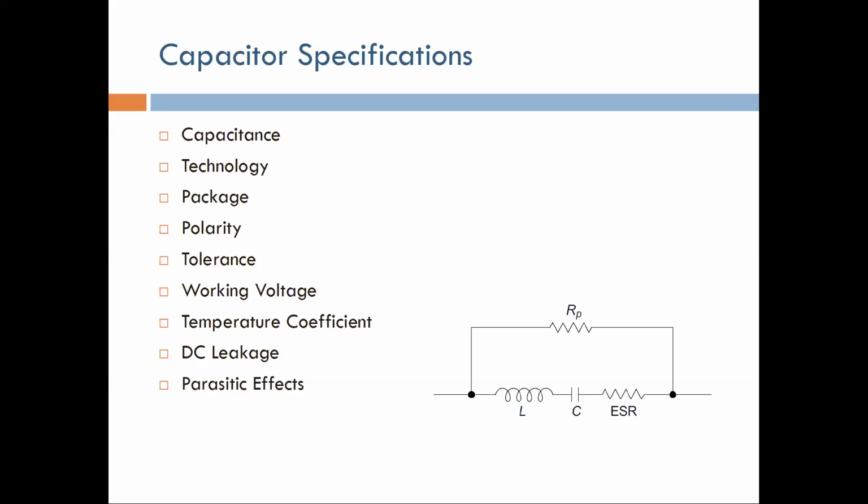The others cannot. One type of capacitor is called a paper capacitor, which is basically like two aluminum foils with a paper, just like a sheet of paper, in between them. You can get some capacitors made out of that, but they are really very small in capacitance, and they are usually large in size. But they are very stable and they are very cheap. So basically, for some applications they can be used, but in others they cannot.